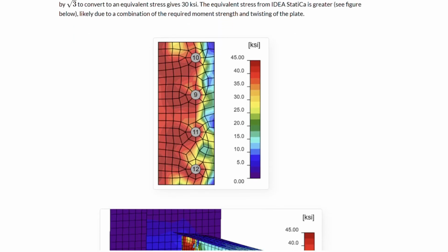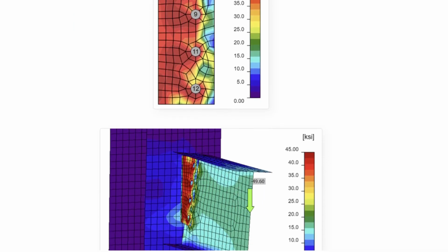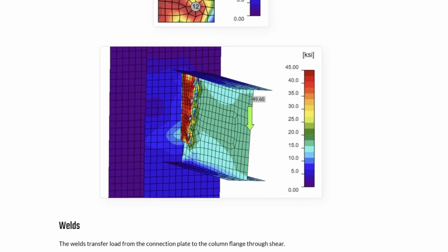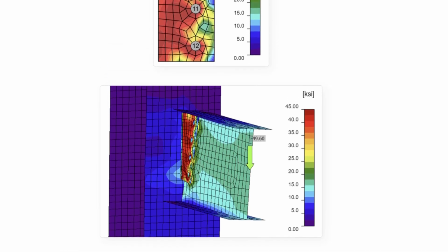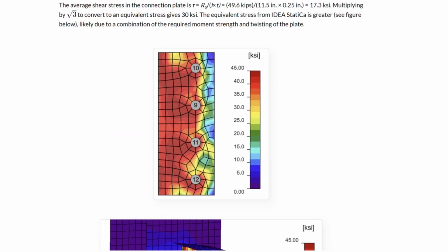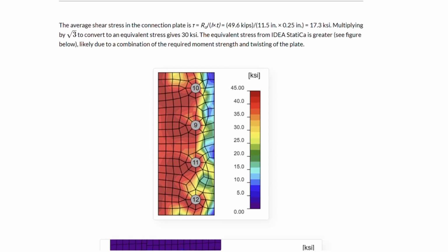Examining the load path helps clarify that the primary purpose of a simple shear connection is to transfer shear force while allowing rotational flexibility at the beam end. By tracking the load path for a typical simple shear connection, engineers can see that the force primarily travels through the beam web, into the bolts or welds, and through plates to the supporting member. The beam flanges are intentionally not engaged as they would be in a moment connection, therefore blocking any potential load paths for the moment.